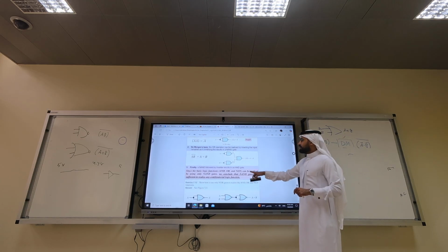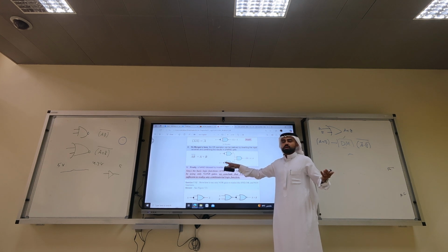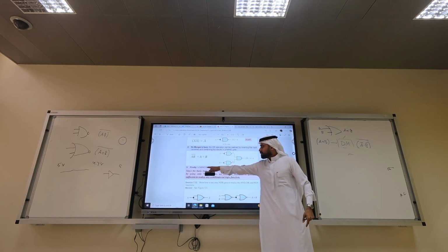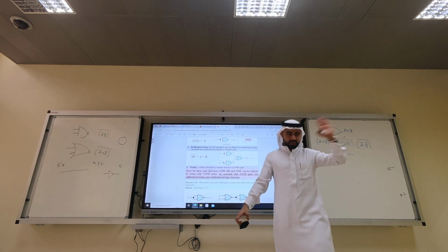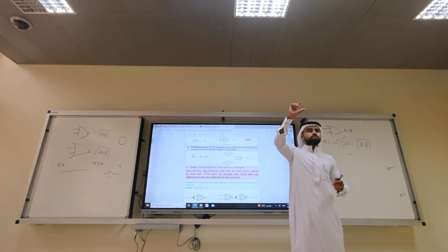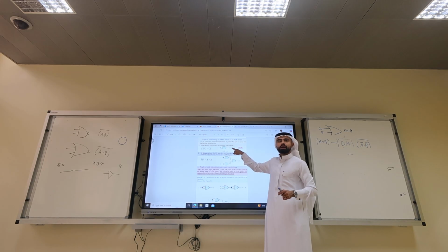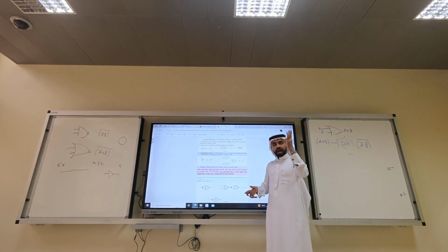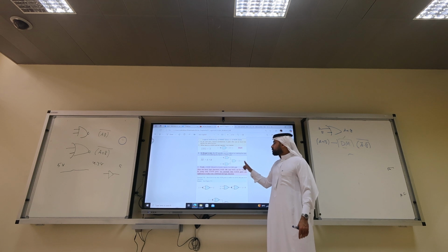Finally, NAND, the last thing is NAND. If you put an inverter after, you can get an AND. So now I can create AND or an inverter using only NAND. So NAND followed by an inverter results in an AND. So in summary, to build an inverter using NAND, what to do? Tie the 2 inputs together and use NAND, you will get the A prime. If you want to implement OR using NAND, you need 3 NANDs. 2 act as inverters, and the last step is the NAND, and you will get the OR.